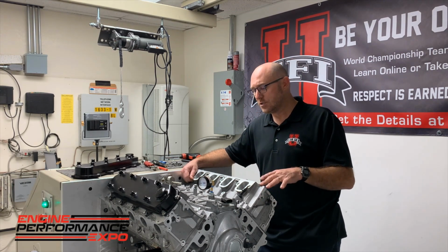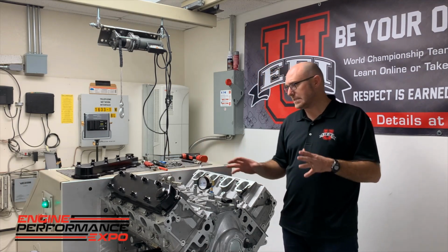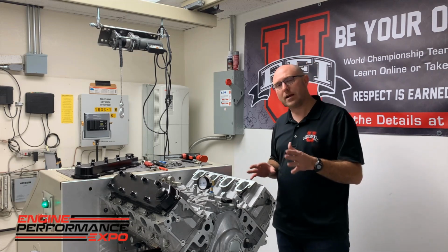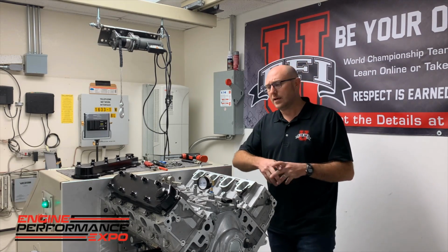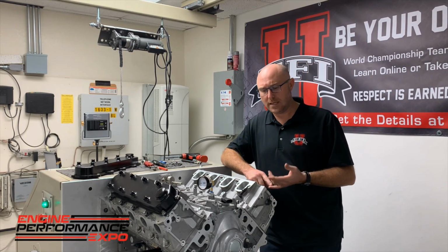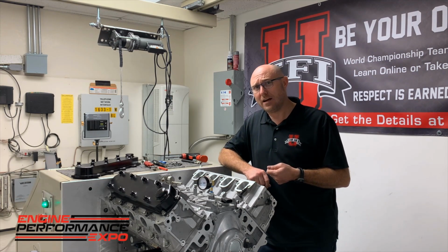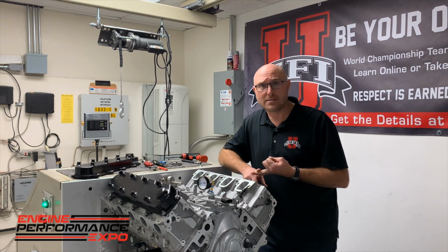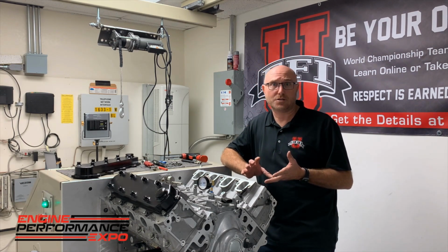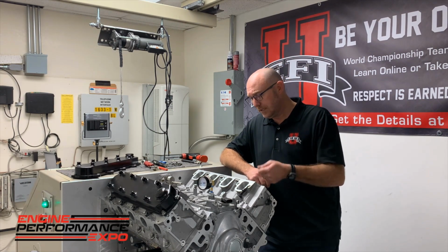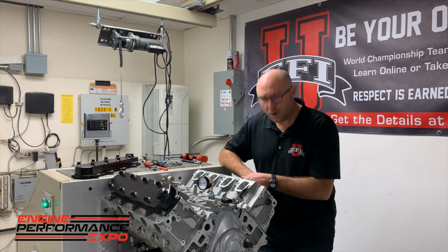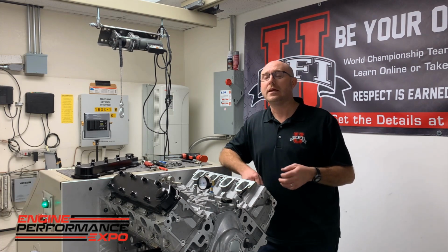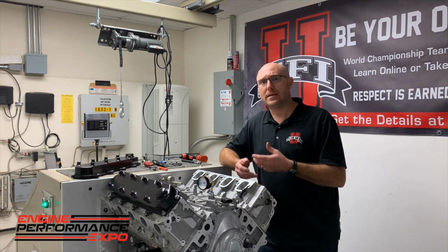So typically, we'll get everything set up, we'll run our first test, we'll pull the valve covers off and just check around and look for stuff. We look for those high danger items, things like, wow, all of a sudden I got a ton of valve lash that I didn't have before. Do I have a push rod tip going away, or a lifter that's damaged, or something happened that I didn't catch, right? I might go through, check all the lash, and as I'm looking, I go, oh darn, there's a little chunk of valve spring in there. That means something's really unhappy. That gives me an opportunity to stop now.